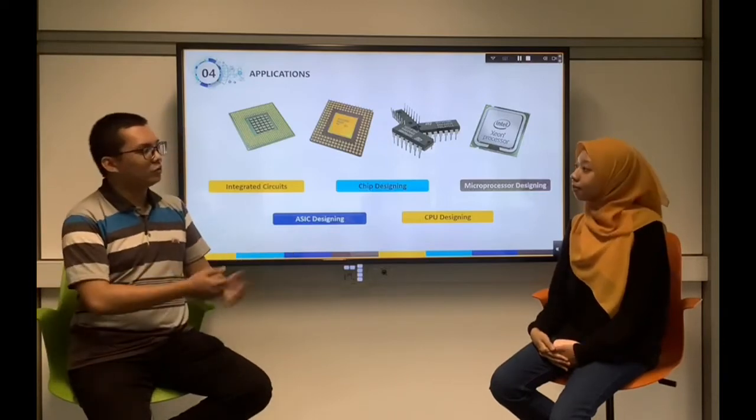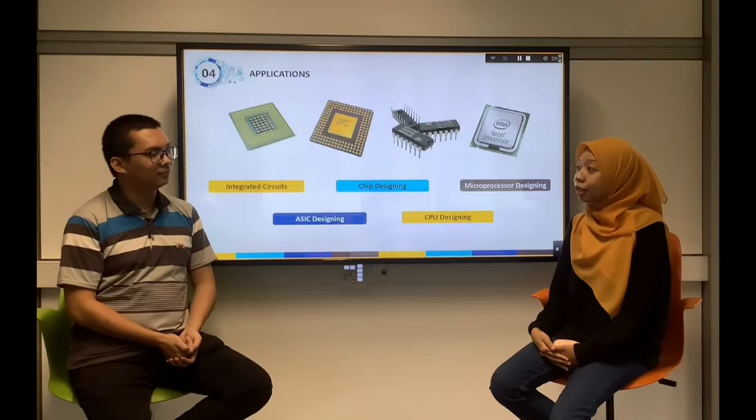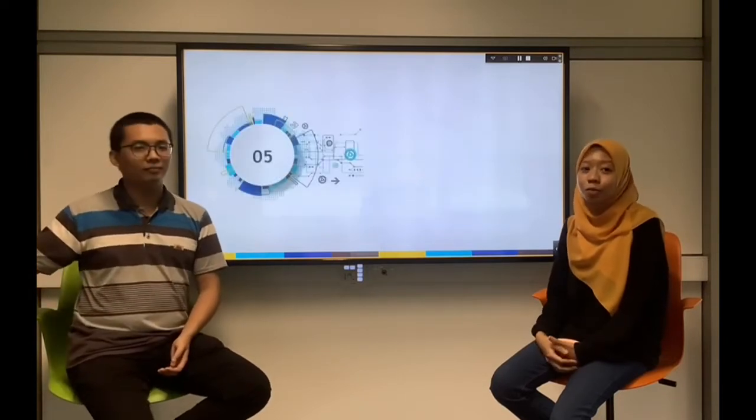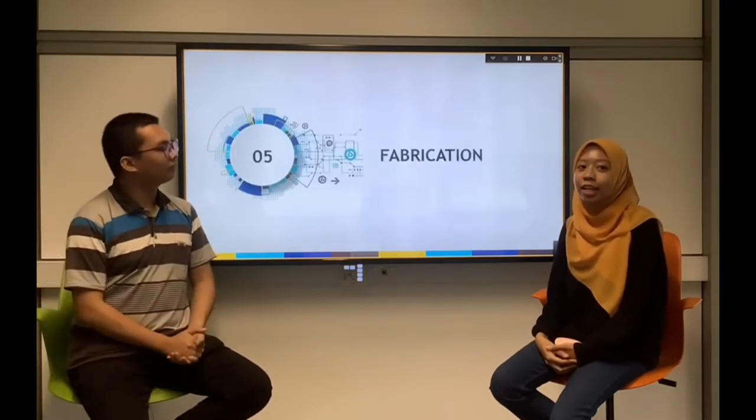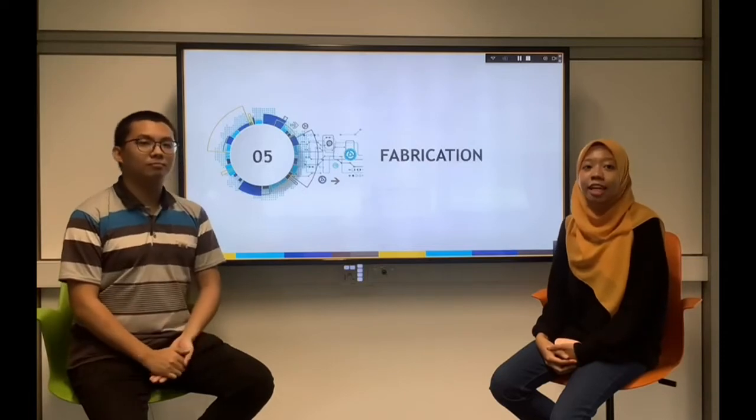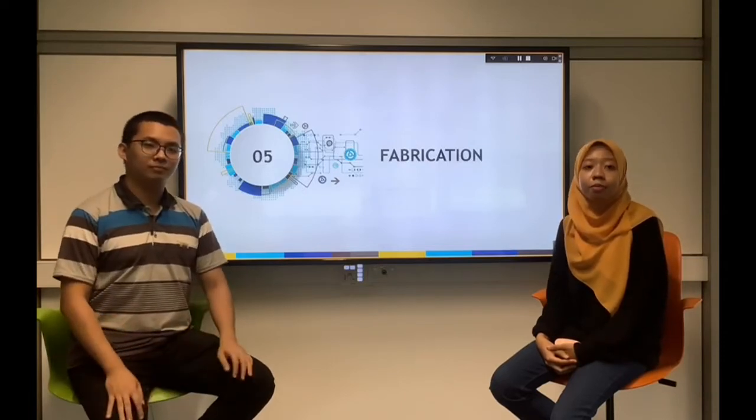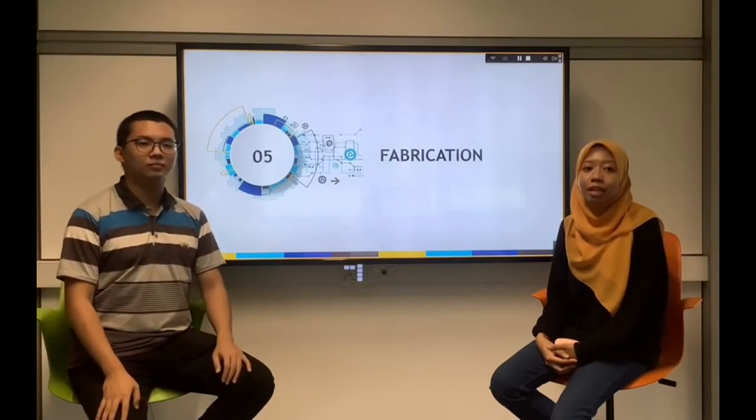But Shraddha, do you know how CMOS is fabricated? Yes, of course. Let's jump to the CMOS fabrication process flow using N-well technology. In N-well technology, an N-type well is diffused on a P-type substrate.